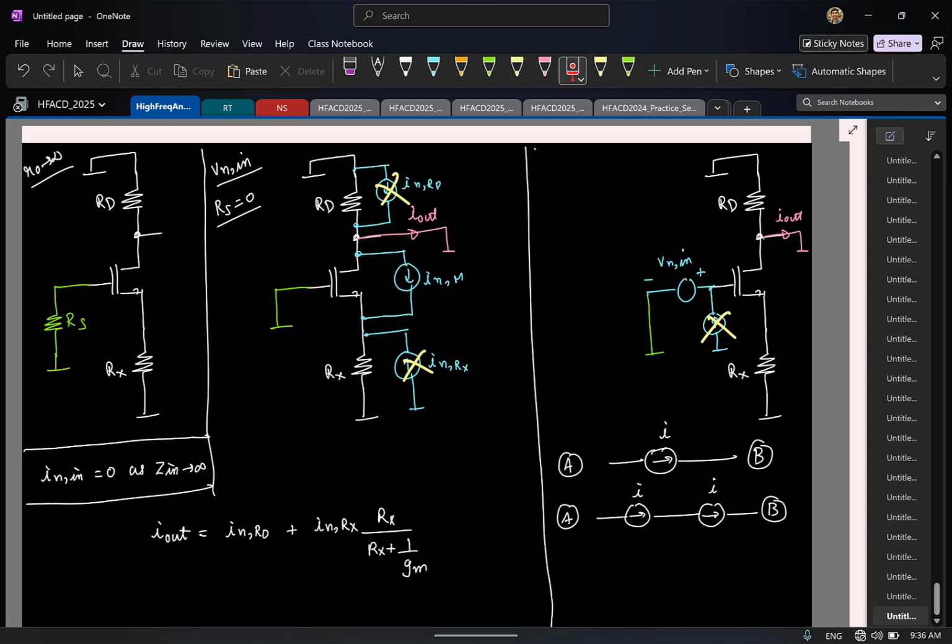Yeah, remember that the reason the calculation here is tricky is because it is connected between two nodes. In my earlier two current sources, it was trivial because one of the terminals was grounded, right? So here if I assume that this is grounded, things are easy, right? So this can be treated this way. I'll assume as though I have one current source connected from node A to ground, and another current source from ground.